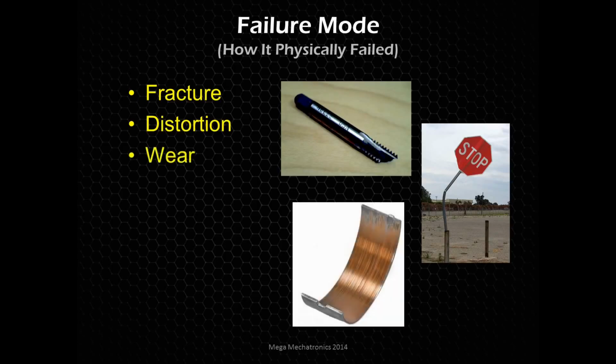Wear can cause lots of problems and lead to catastrophic failures or even fractures. So this is a bearing that's probably from an engine. When a rod bearing blows out, then you start heating up your crankshaft and you can even break your crankshaft from the excessive heat, which ruins your heat treat and fatigue protection.